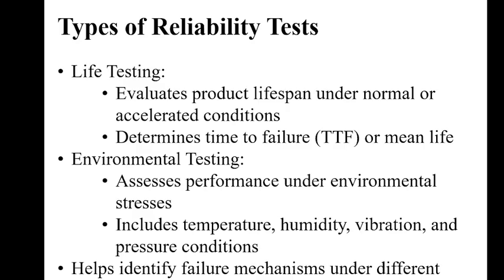Okay, reliability testing generally includes different types of tests, with life testing and environmental testing being two of the most important. Life testing focuses on determining how long a product can operate before failure, either under normal usage conditions or through accelerated testing methods. This helps estimate metrics such as time to failure and overall lifespan.